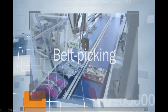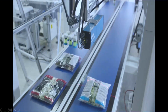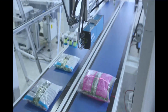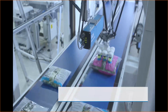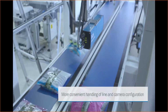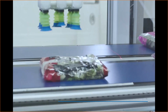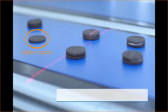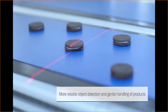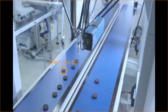Belt picking: you see here our 3D vision sensor, our Trispector, and you can see hopefully a laser line running across the object there, but also the blue belt. It's using that 3D laser triangulation method to produce the three-dimensional image to get that height data. We can have many different recipes or jobs saved there to cope with different types of products. Here you see a bag that could vary in height as well as shape, and these smaller food-based items also vary slightly in height and could be incorrectly produced to be too thin, there is the example.